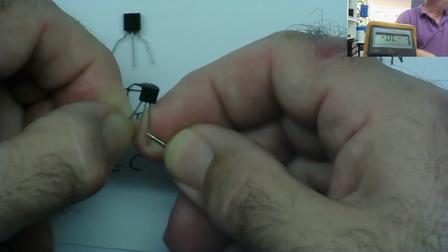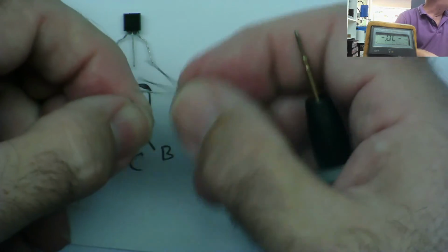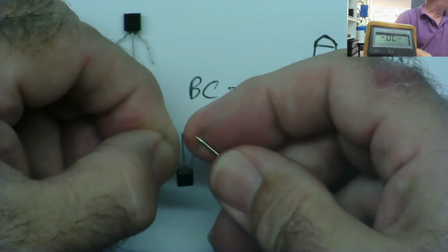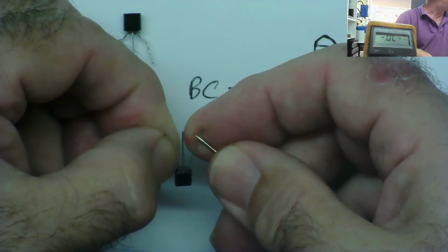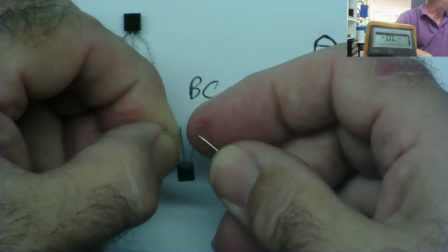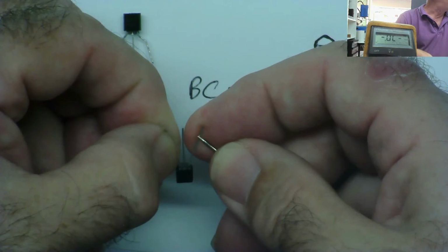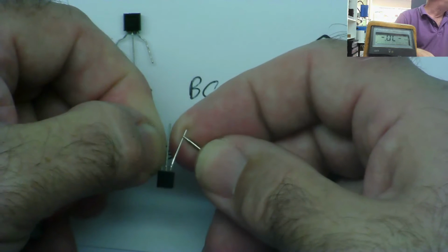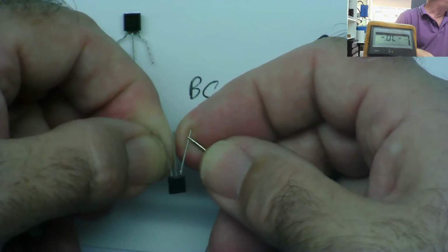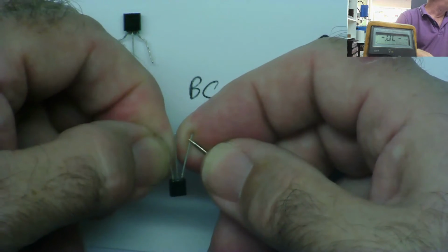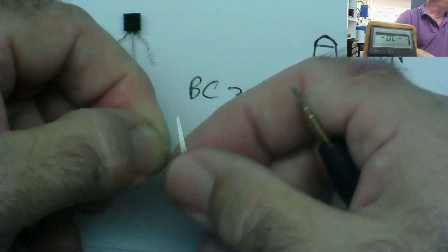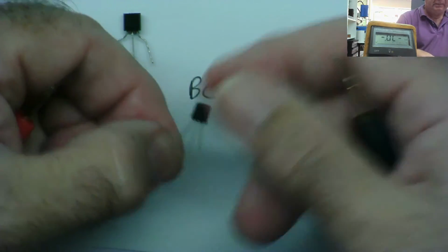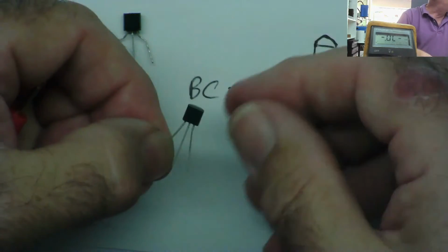Did I mention leakage? That's another way transistors can fail. They can go leaky. I forgot to mention that one. Transistors can go leaky, so that when they're turned off, they're not fully turned off, yeah. Imagine that thing with the water pipe where we have a control narrow pipe and a big pipe if you watch the earlier video, otherwise you haven't got a clue what I'm talking about. Imagine the big disc that closes off the main supply. It's got a rubber seal and the rubber's worn, yeah, so it leaks. Same thing happened with the transistor. Okay, so there's no leakage on this one.